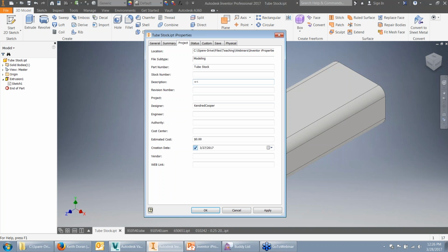The catch with this is you have to type it in exactly. So if you have capital letters and underscores in your parameter name, you've got to put them in here that way as well. I can't do a lowercase w for width. I actually used an uppercase W, so I have to recreate that here. So with uppercase W, label or call out the name of the parameter width, and I close it with the greater than caret. So equals caret width caret.